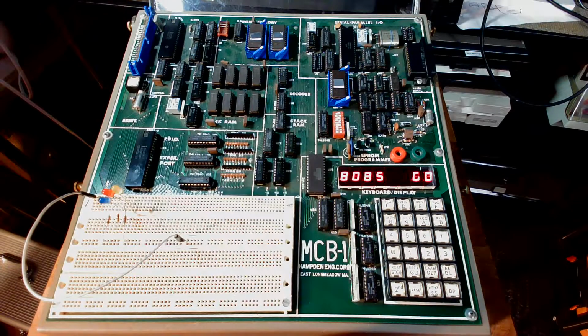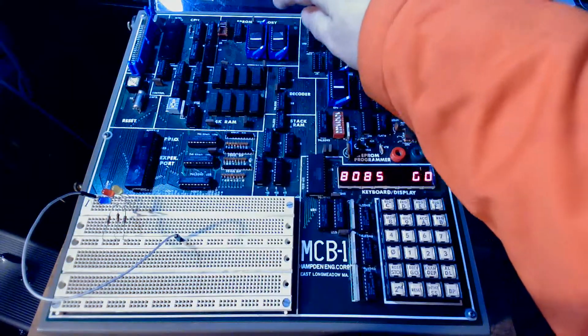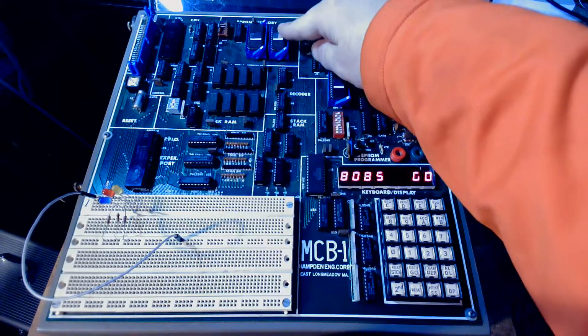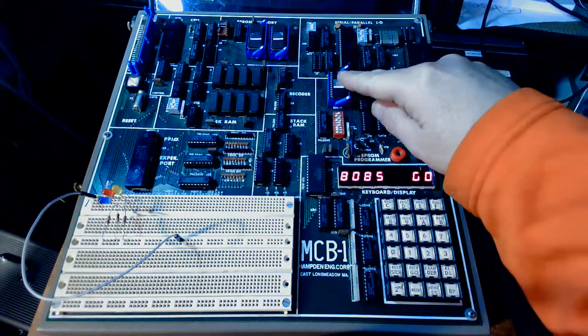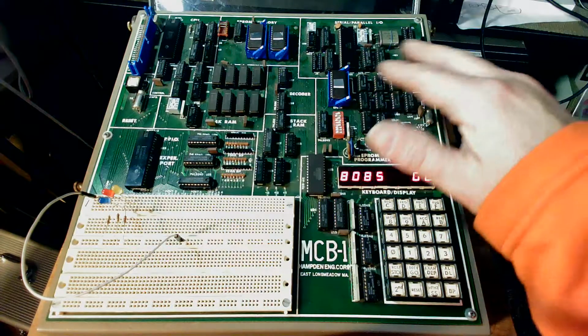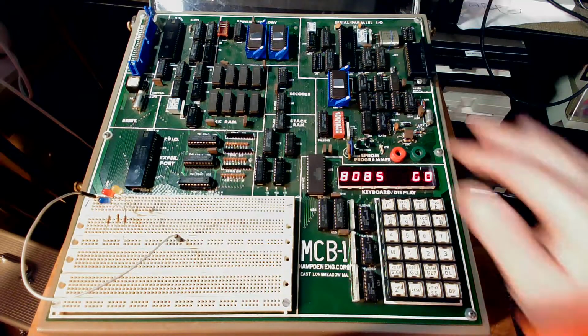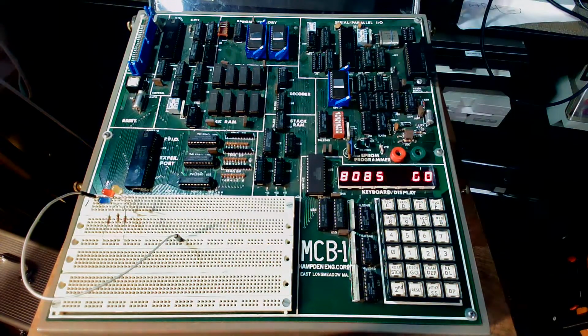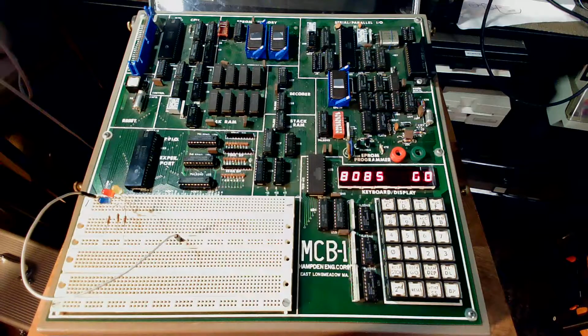So this is a highly configurable machine. This is the OS ROM really. This is a user supplied ROM. It's optional, right? So I simply have a copy of the OS ROM here. And then this is really an EEPROM burner. I wasn't able to use the EEPROM programmer, so maybe there's some defect here. But as a ROM, it works perfectly fine if you put a 2716 in there.